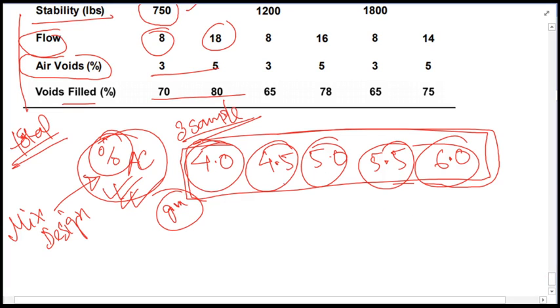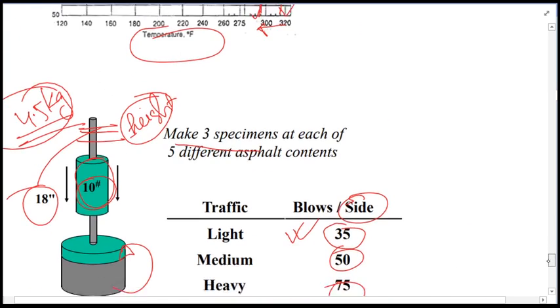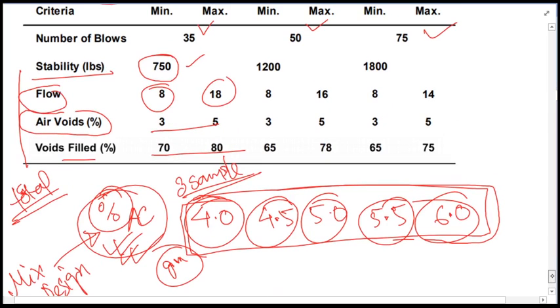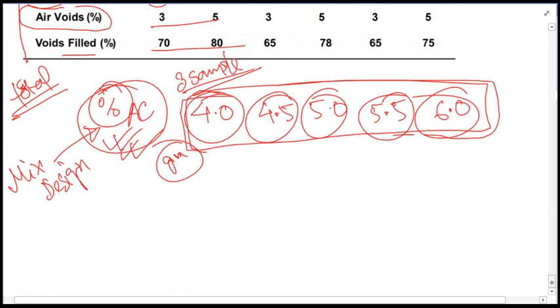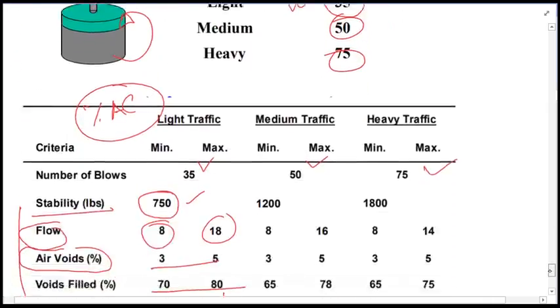So that's how we'll have to proceed. Now, if you make these 5 asphalt contents, you will plot graphs, and from the graphs we will try to see whether the criteria are satisfied or not. Generally, using these 5 asphalt contents, all the other features will meet their criteria, which we will see afterwards. In general it satisfies, and if not, then what will you do?